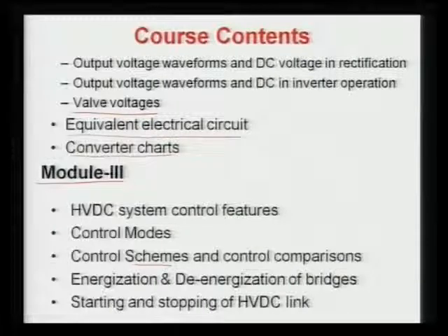Another lecture will be dedicated to the energization and de-energization of bridges. If your HVDC link has more than two bridges on the converter side or inverter side, and you want to take one bridge out of operation for maintenance or other purposes, then how are you going to de-energize it, how are you going to bypass that bridge, and once it is repaired, how are you going to put it into the HVDC link again. So energization and de-energization are discussed in detail in this module 3 as well.